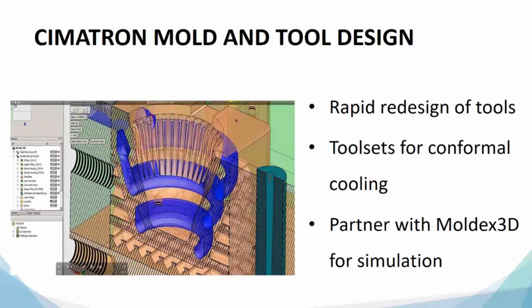One of the things that the printing process gives you is the ability to do these infills where you're not putting printed material in an area that's of no real effect. So you can minimize and reduce the cost of the machine time, the cost that goes into the printed material, by doing this sort of an infill pattern. That depends upon what you're doing, right? What the mold is and what that area of the mold is going to experience.